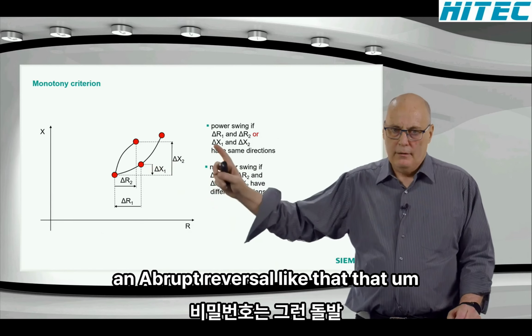The smoothness criteria is a very commonly used one to check, because that's also a very interesting one. The distance between each of these measurements, remember, every 5 milliseconds you measure impedance, is going to be fairly constant because the rate of movement is quite constant. And it's also interesting, I didn't mention that earlier. If you remember that circle we had before with 0 degrees at the top, 180 at the bottom, the movement when you're close to zero is fast.